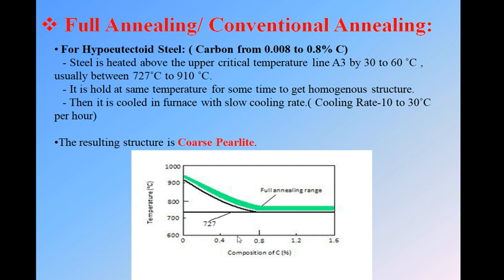Okay, for 0.6% carbon steel we can heat it up to this temperature. Okay, this may be 780 to 800 degrees Celsius. So the temperature zone will change as per your carbon percentage.